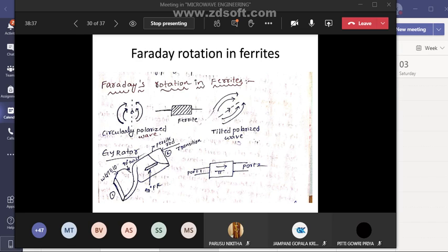So when the same wave enters at port 2, it undergoes a Faraday rotation through 90 degrees in the same direction, because the twist in the waveguide rotates it by 90 degrees in the anti-clockwise direction, and it comes out of port 1 with 0 degrees phase shift. Right? So this is about the gyrator. So first, what is the Faraday rotation principle?